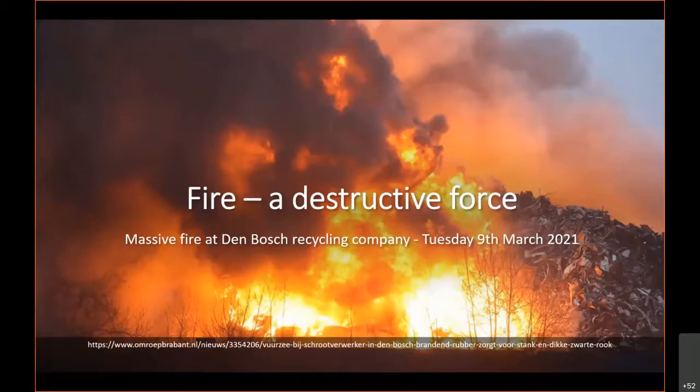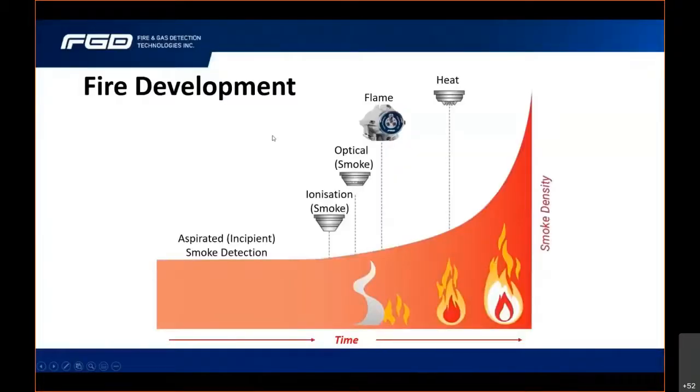How do we provide something that detects fire at an early stage? And there in itself, I've used the word detect. So by understanding the growth phase of a fire itself, we can apply different types of fire detection technology. If we're looking at a very, very early stage, perhaps in a clean type environment like a data center, then we might use the aspirated type smoke detection system that would be linked directly into the control cabinet of each of those data packs themselves.